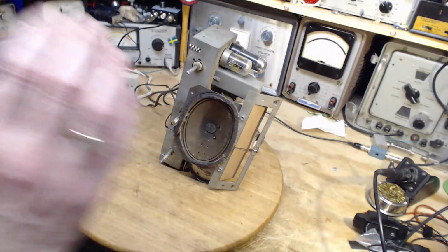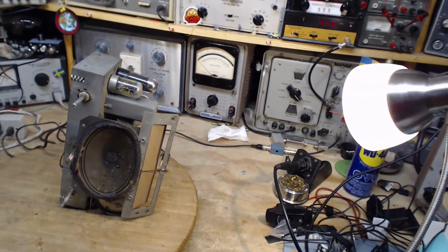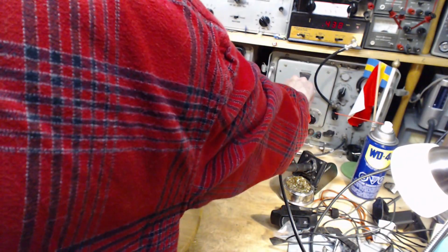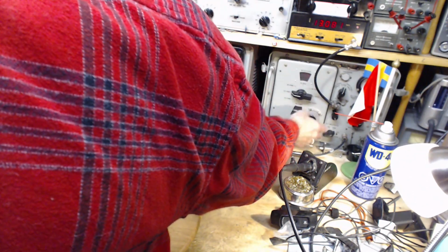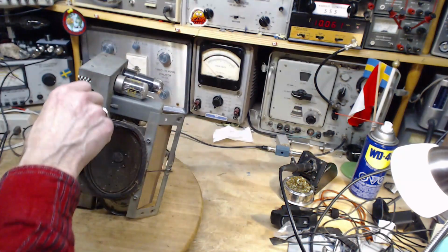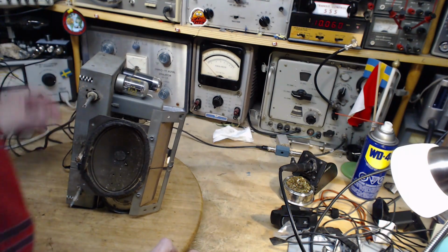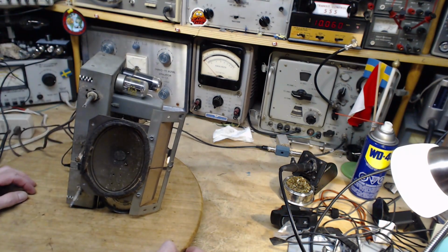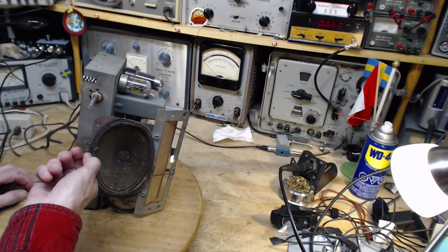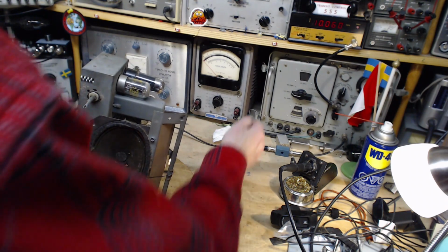So right now, the signal generator is transmitting a very strong, like strongest antenna signal you would be likely to get over to the radio. But look, it's at the IF frequency. We want it up around 10. Okay, so I'll turn the volume right up. Double check. Definitely connected. Okay, and I'm going to tune it this way a little bit to make sure it's well above 10 now, because 11 was roughly in the middle, so this might even be up around 12.